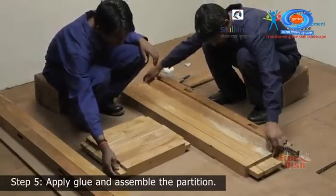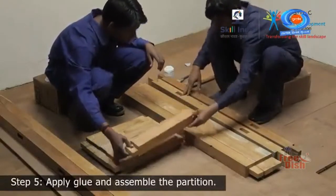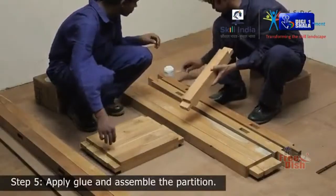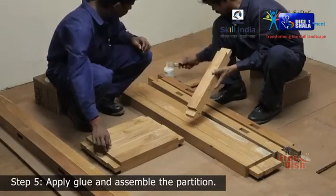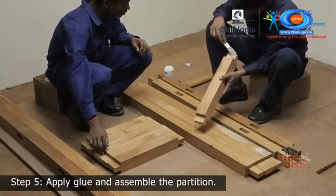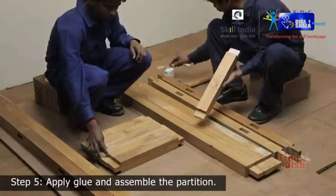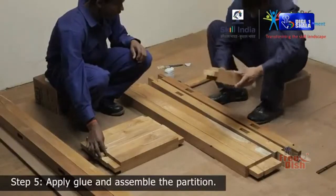Step 5. Apply glue and assemble the partition. First, place a stud member with 2 grooves on the floor and apply glue onto the mortise and on the tenons of the noggins and start fixing them one by one and tap them lightly with a hammer to fit in.